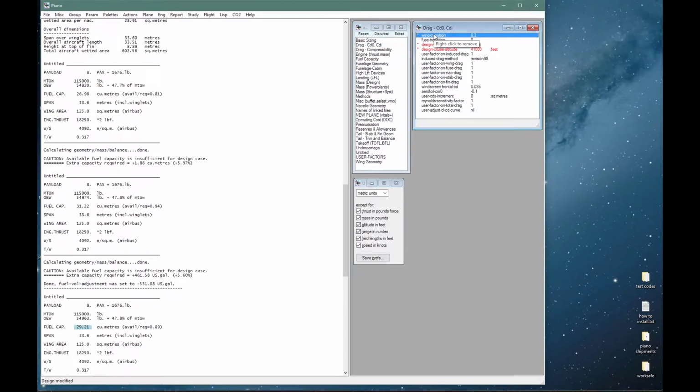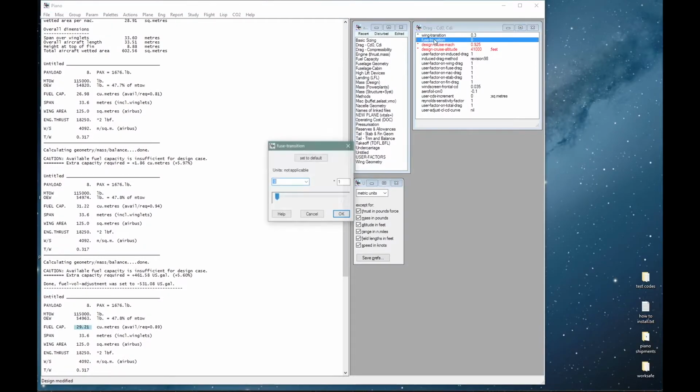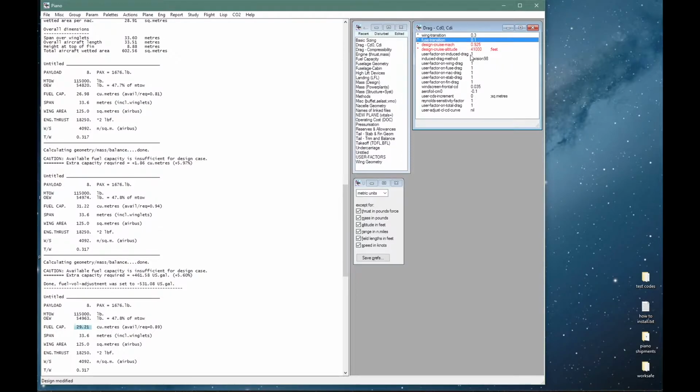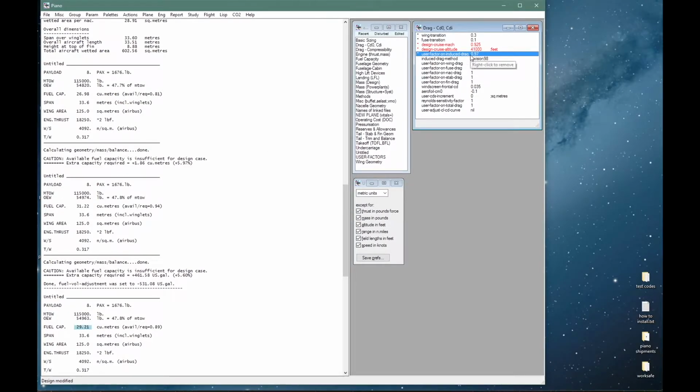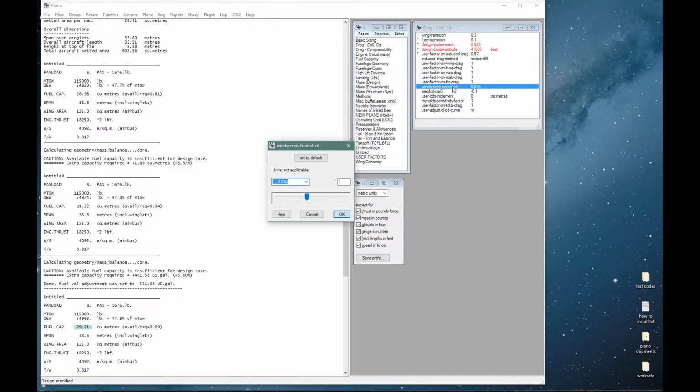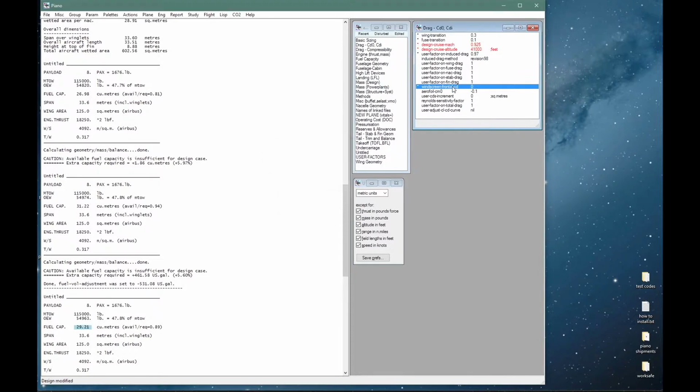This is just an effective value that would in reality vary across the span. You could think of it as an indication of aerofoil technology level. Similarly, for the fuselage, I will set the transition at 10% of the fuselage length. I will apply an induced drag factor of 0.97 as before, and when I say as before, it just means that I've used something similar during previous lectures. And also set the windscreen frontal CD to 0 as before.